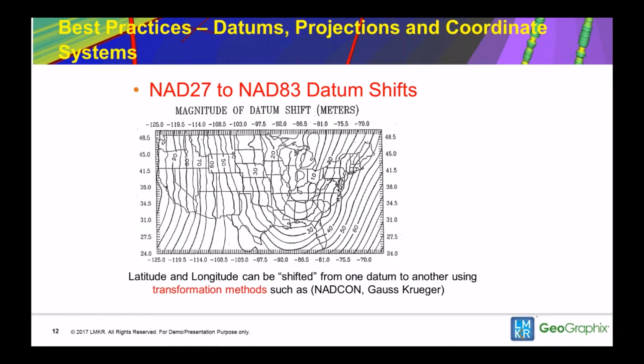So you sort of have to remember this and be aware of it when you get a well spot or any sort of spatial data that has lat long associated with it. First thing you need to ask yourself: what datum? If you don't ask yourself what datum, you will get a considerable error. Sometimes it doesn't mean that much, but when you get to 150 to 300 feet, it means quite a bit. And of course, depending on where your bottom hole location is with all the horizontal wells, it could be much, much more than that. So it's good to understand this kind of stuff.